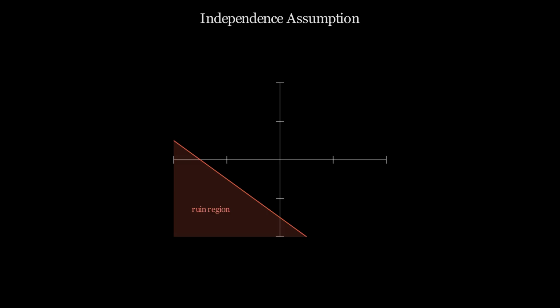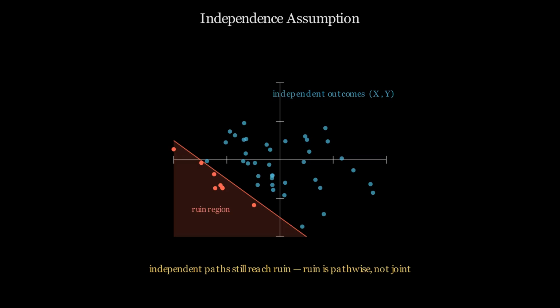Independent component design assumes zero correlation between failures as a source of safety. Statistical independence between failure modes is treated as sufficient to eliminate common risk. This assumption shapes redundancy architecture and reliability analysis.